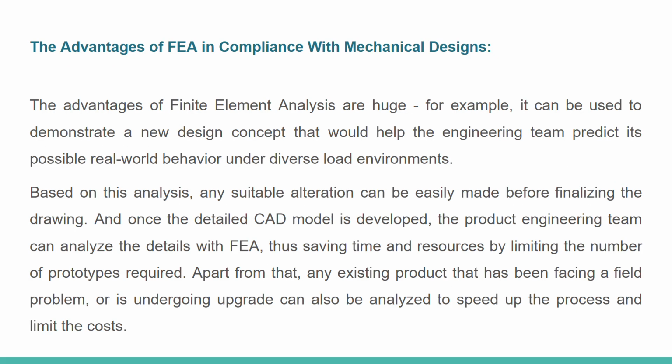Next, the advantages of FEA in compliance with mechanical designs. The advantages of finite element analysis are huge. For example, it can be used to demonstrate a new design concept that will help the engineering team predict its possible real-world behavior under diverse load environments. Based on this analysis, any suitable alteration can be easily made before finalizing the drawing, and once the detailed CAD model is developed, the product engineering team can analyze the detail with FEA, thus saving time and resources by limiting the number of prototypes required.